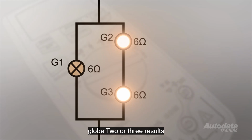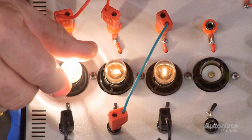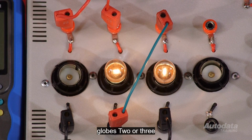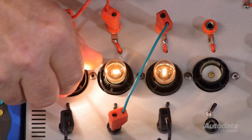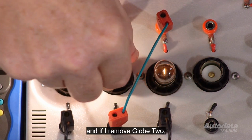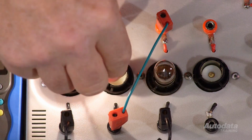Failure of either globe 2 or 3 results in the other globe not working, but will have no effect on globe 1. If I remove globe 1, it has no effect on globes 2 or 3. And if I remove globe 2, globe 3 goes out, but has no effect on globe 1.